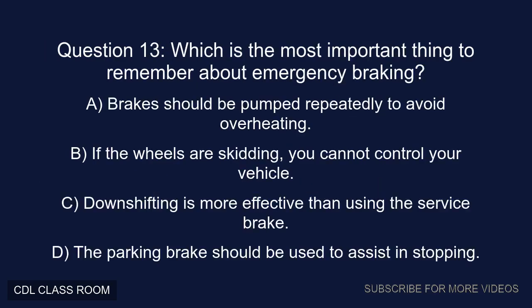Question 13. Which is the most important thing to remember about emergency braking? A. Brakes should be pumped repeatedly to avoid overheating. B. If the wheels are skidding, you cannot control your vehicle. C. Downshifting is more effective than using the service brake. D. The parking brake should be used to assist in stopping. Correct answer, B. If the wheels are skidding, you cannot control your vehicle.